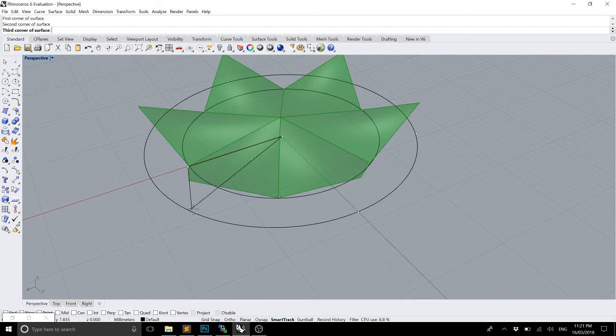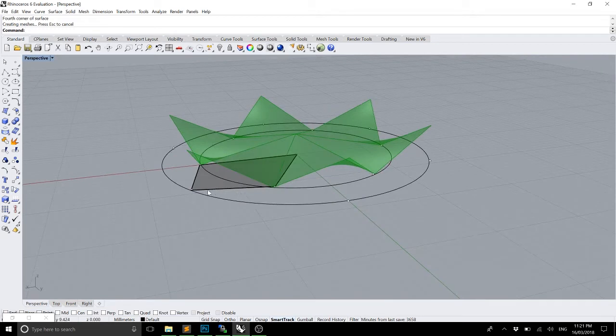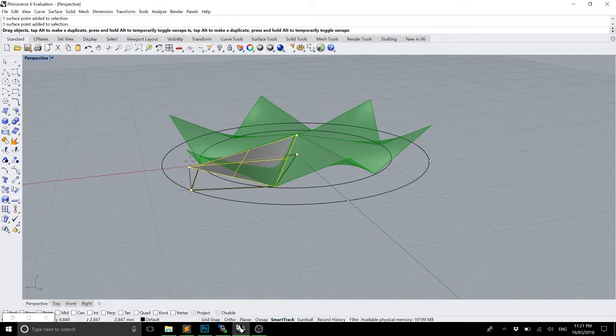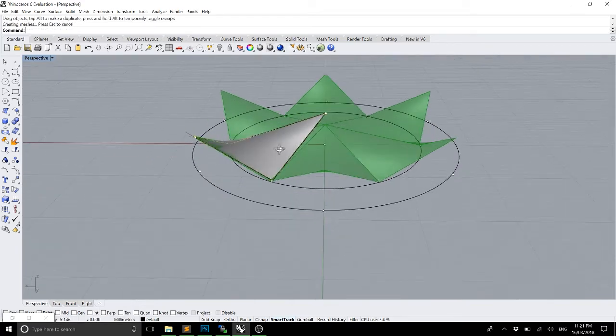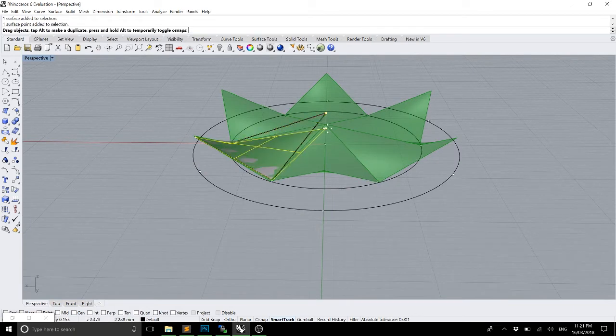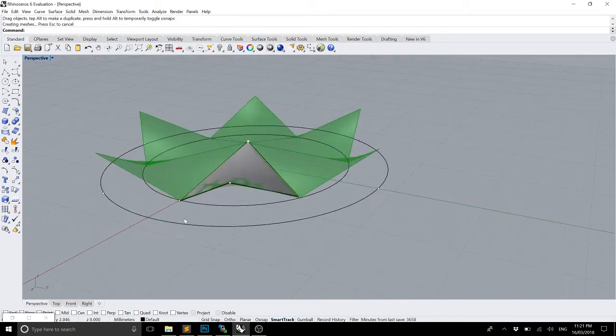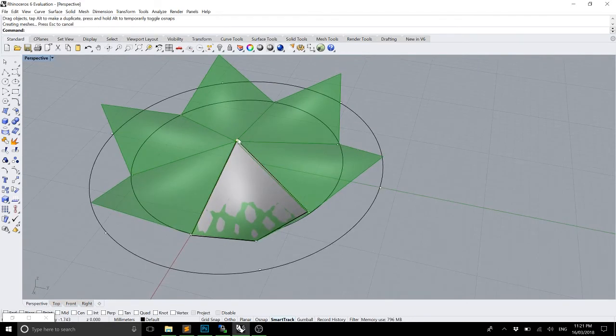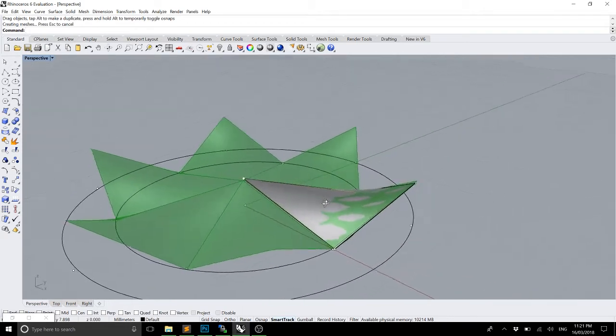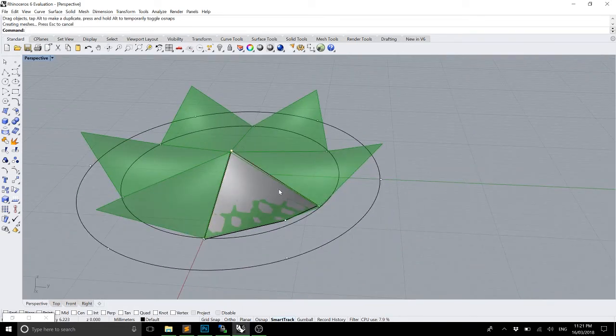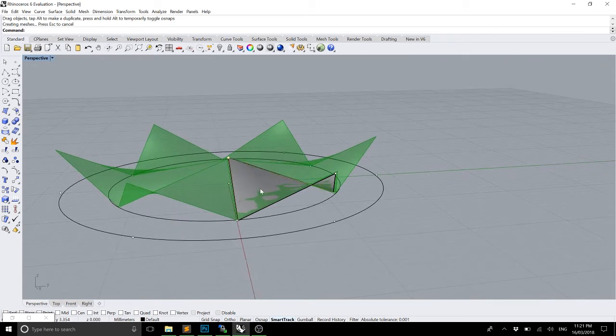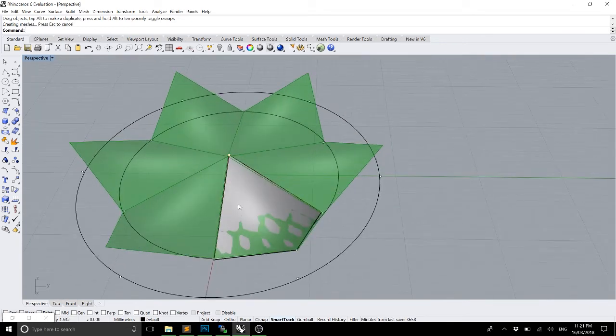So if I just use Rhino to do that, then here's a 4-point surface, and if we were to then control that surface in 3D, we're effectively moving 2 points vertically. If you have a 4-sided shape that isn't planar, then you can resolve the geometry of that shape by making it a hyperbolic paraboloid, which is what we're looking at here.